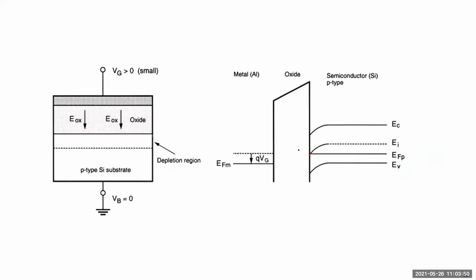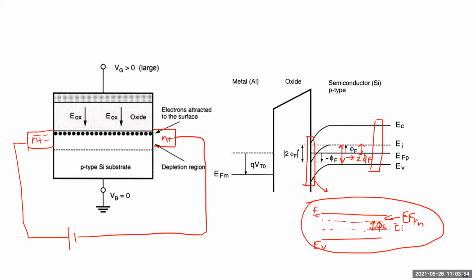And then you apply the voltage to take care of the depletion, and then you apply the voltage to make the surface potential equal to minus Vf, such that the total is 2 Vf, and that's the inversion. And I was explaining yesterday that if you look at the slice here, it looks like N-type. Now, in order for it to look N-type, this V has to be exactly in the opposite direction by the same amount as it was in the P.